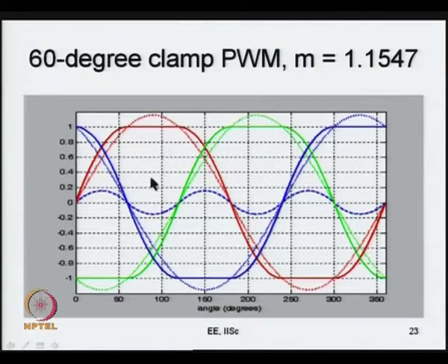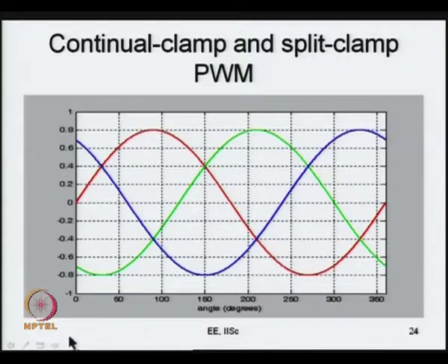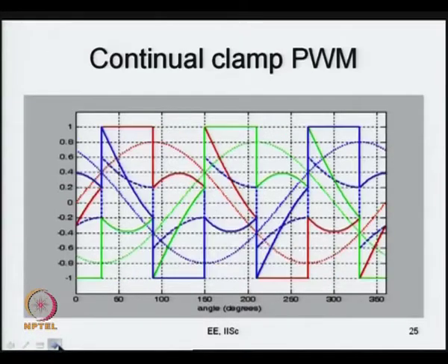If R phase current is going through a 0 crossing here, not much saving is obtained, and if R phase for example has its peak here, when R phase is switching, not much is obtained here. So, you have this thing of phase shifting which you can normally do. Now for example, if the R phase in this case, let us say the current is a little leading, then you can go in for a clamping as shown here now.